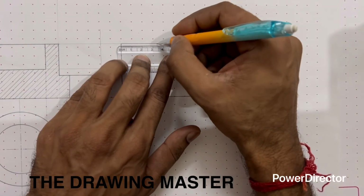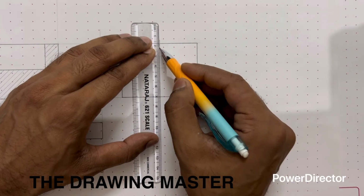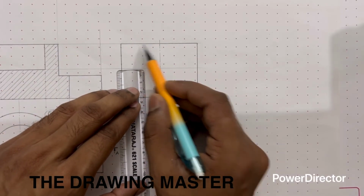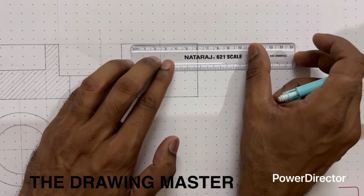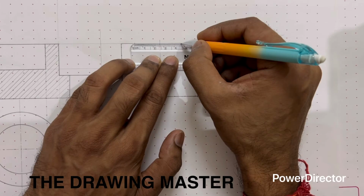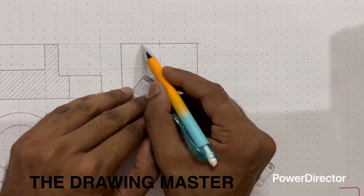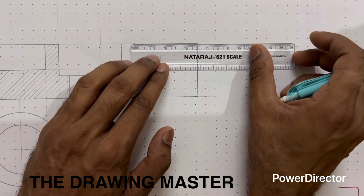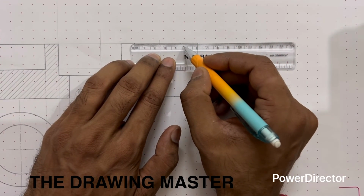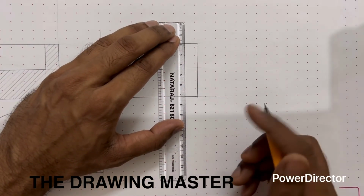So let's mark the center line. Out of 72, this is 36 and 36. This is the center. Now the diameter of the hole is 48, means 24 this side and 24 this side. And this side again 24. So 24 this side, 24 this side. Yes, it should be here. So now we will prepare the depth of this hole here.